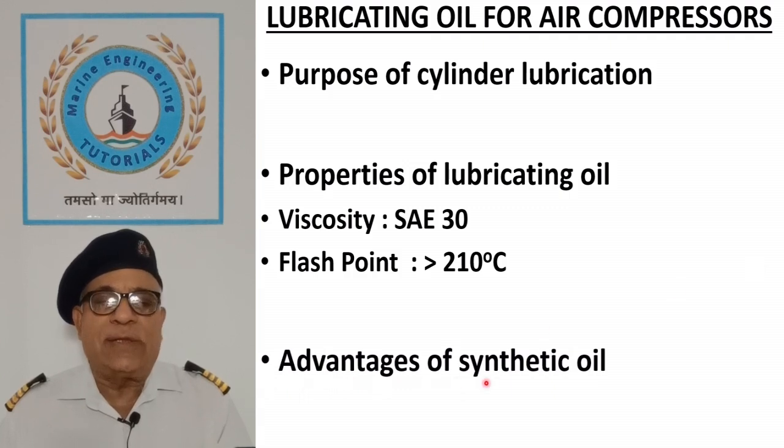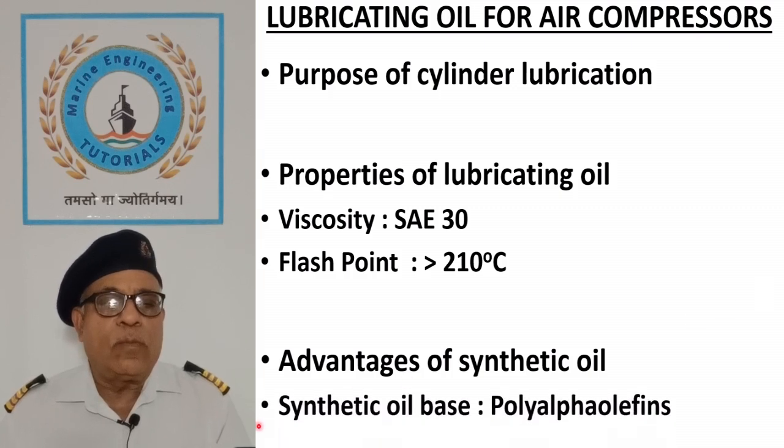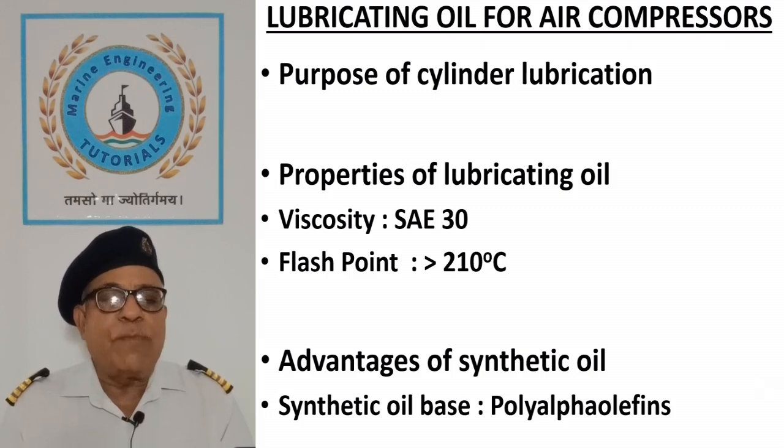Advantage of synthetic oils. Nowadays, synthetic oils are preferred over mineral oils due to their superior performance. They offer long life, low volatility, low oxidation rate, etc., although they are more expensive in comparison to mineral oil. Synthetic oil base. Most of the synthetic oil for reciprocating compressors are manufactured from polyalpha olefin base.